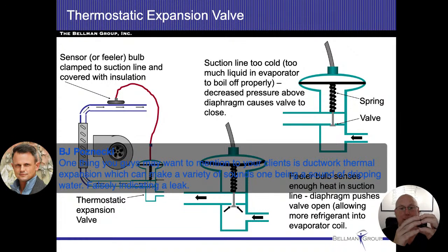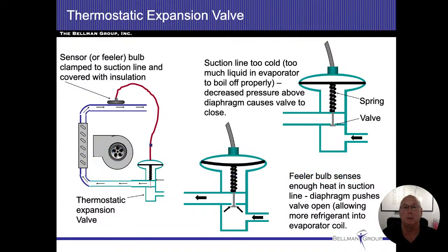And so what's happening is the ductwork is getting warmer, it's going to expand. As the ductwork gets colder, it's going to shrink. I'm sorry, BJ, I didn't understand what you were mentioning to me when you said thermal expansion before. As that's shrinking and expanding, there's pieces that are going to slide in between each other. And it's just going to be a little bit of movement as it comes through it. So sometimes it sounds like dripping water that happens in there.